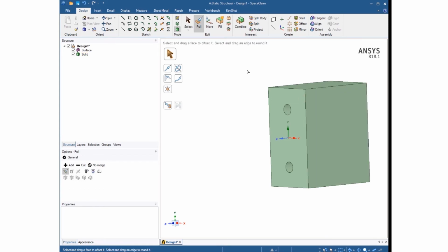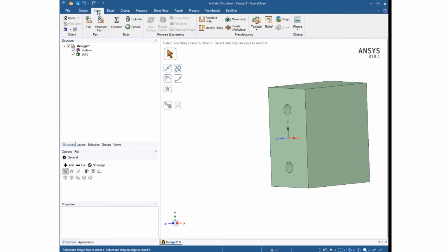I'm ready to import the truss. So I'll come to insert, and here it's nice, you can insert a standard part and look online. These two websites, when you click on them, are great websites for finding IGES files for brackets, for bolts, for nuts, for hangers, for wheels and rollers, and many other objects that you may want to use in a design or a model. I've already gone to these websites and downloaded them and saved them as IGES files.